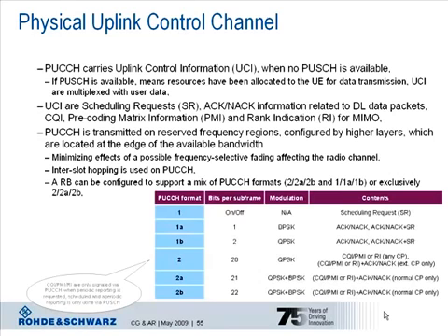A physical uplink control channel is only issued by the UE when no uplink data transmission is ongoing. In that case, the user data and uplink control information is multiplexed onto the physical uplink shared channel. That means one UE is only issuing a physical uplink shared channel or a physical uplink control channel, never both.